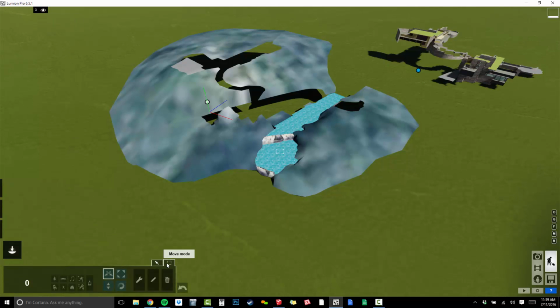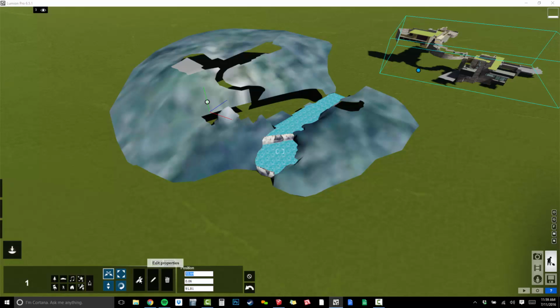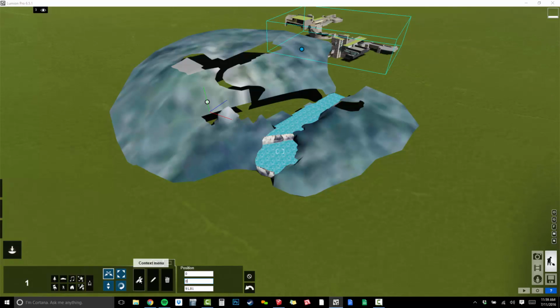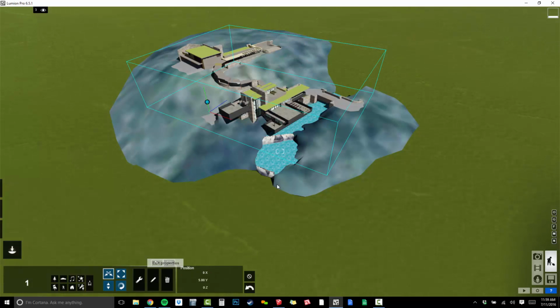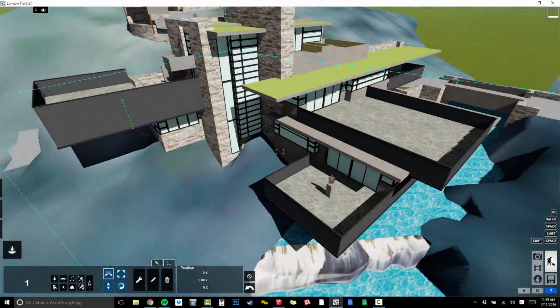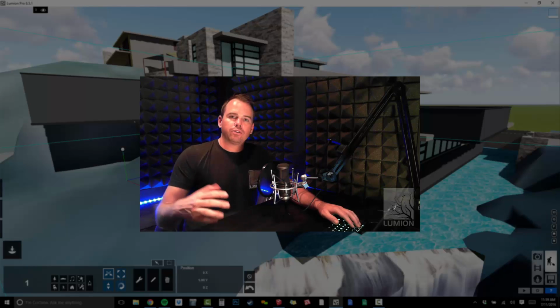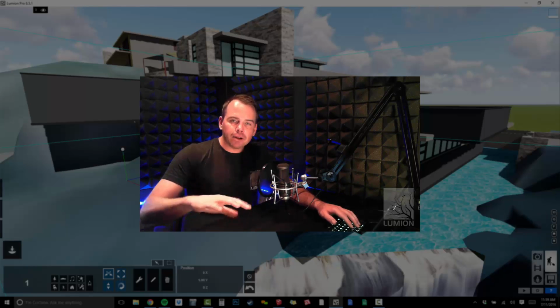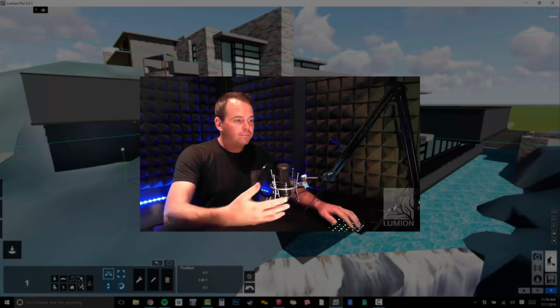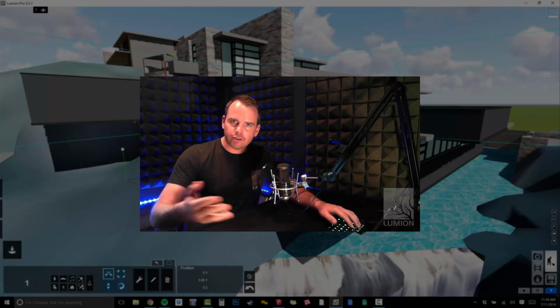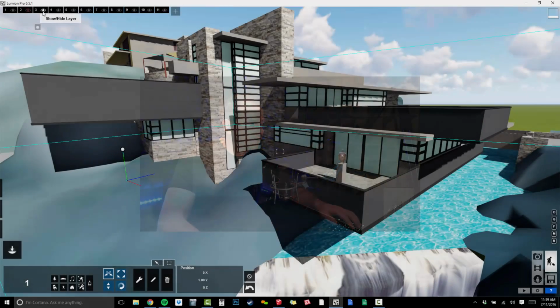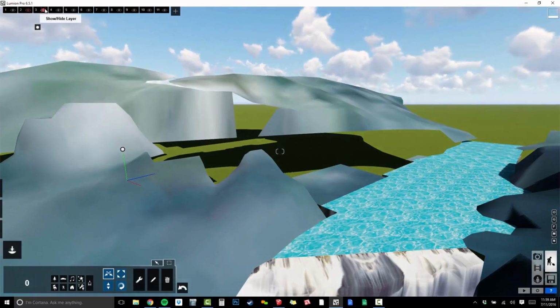And if I go to move mode, let's see, select this guy. There it goes. And I'm going to go to 0, 5, 0, like that. So now those two buildings are literally stacked right on top of each other. So that's going to cause some issues with some screen flickering. I'm going to need to be aware of that and make sure that those layers are turned off at the right time. So for this building B, I could turn that one off.